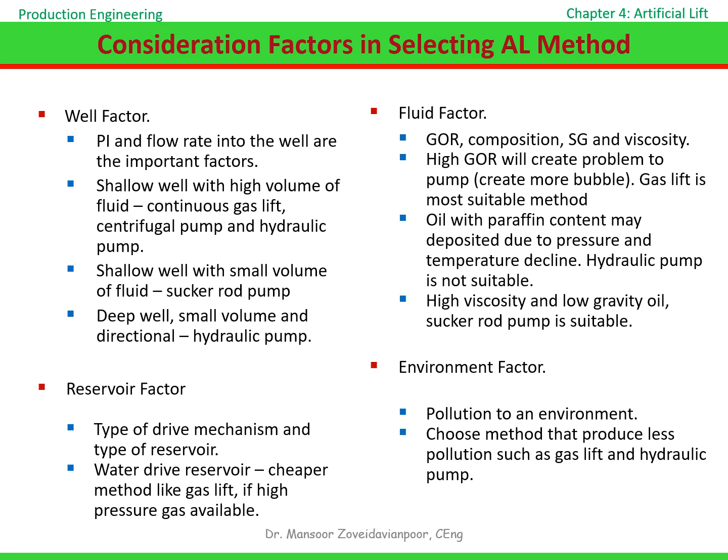Gas lift handles free gas extremely well, which is one of its major advantages. We also need to consider issues such as viscosity, fluid density, paraffin deposition, and fluid composition. For example, highly viscous oils may favor sucker rod pumps, while paraffin-prone systems can create problems for certain hydraulic pumps.